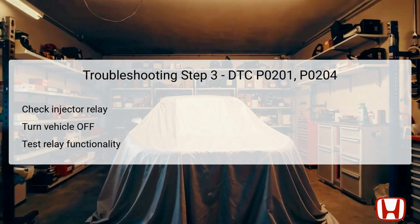In this step, the focus is on examining the injector relay, which is crucial for electrical supply to the fuel injectors. Begin by turning the vehicle to the off mode and then remove the injector relay for testing. Proper functionality of the relay must be confirmed, as a malfunctioning relay can prevent sufficient power from reaching the injectors. If the relay is found to be in working order, you will proceed to the next step.